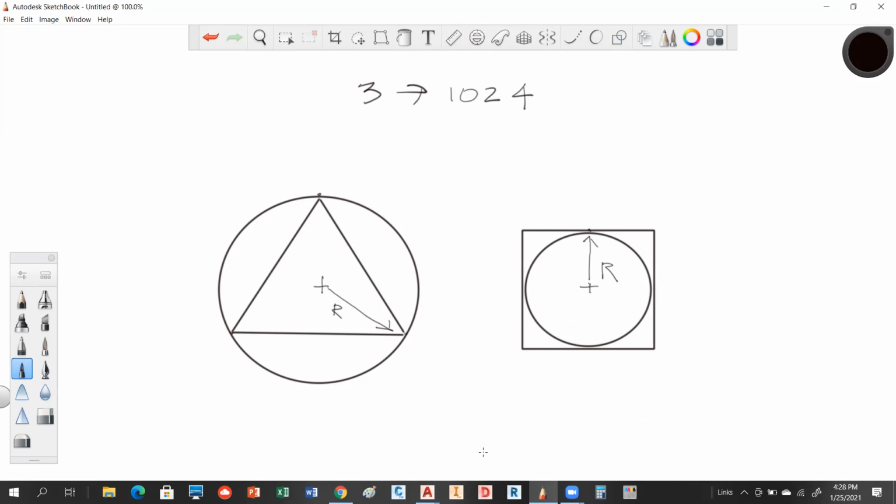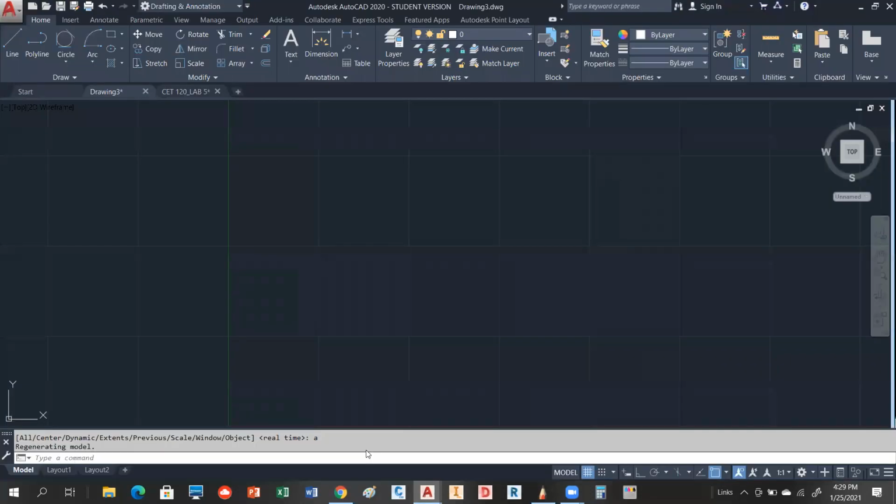They're pretty simple. So if we go back to AutoCAD, and we go to this guy called your polygon, the first thing it wants to know is the number of sides. I think if you've never used it before, it always shows up with 4. But once you've generated a polygon, it will actually remember them. So unless you want to change that, it'll keep that number. So we're going to make this maybe a 10-sided. And by the way, that has to be an integer number. So you can't have 10.5 sides, or something outrageous like that. So I'm going to put 10.